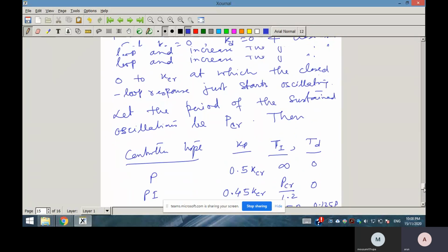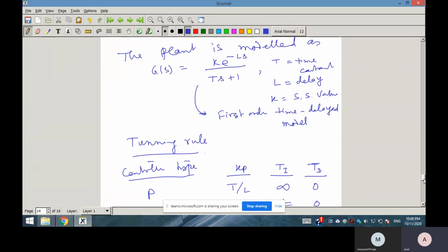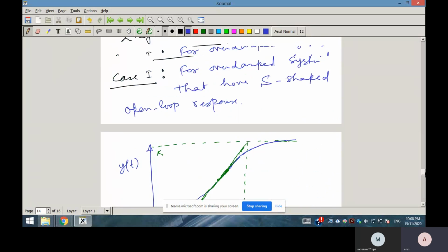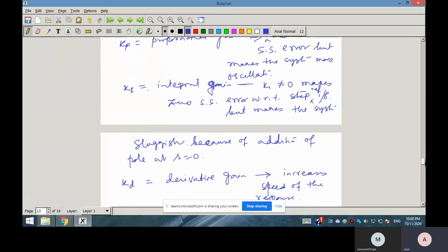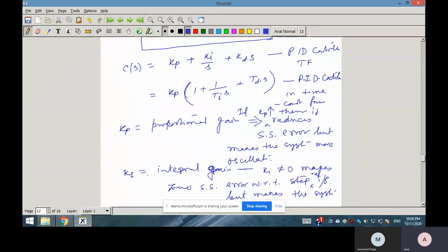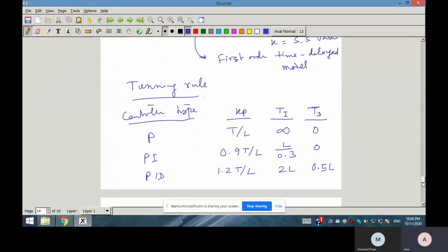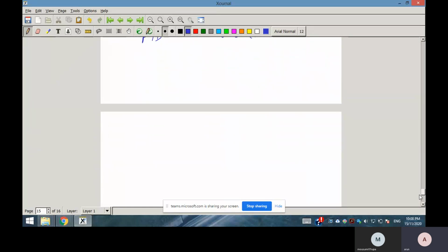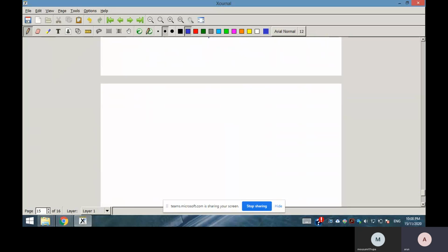But the main problem with the PID controller occurs because of this improper function, KDs. How will you realize this improper function? Even if you can use a differentiator to implement this, it will cause a lot of problems in practice. So how to avoid those problems? Practical implementation.